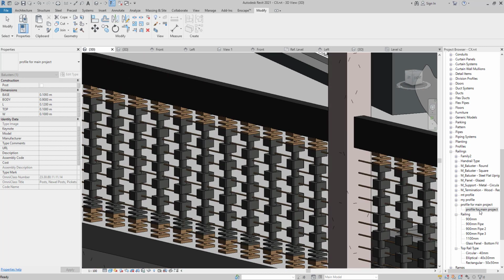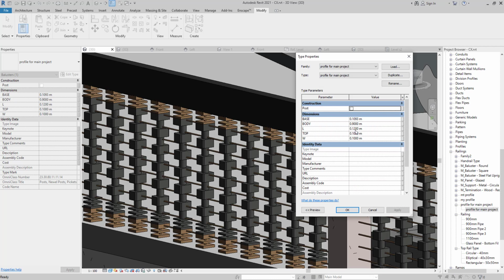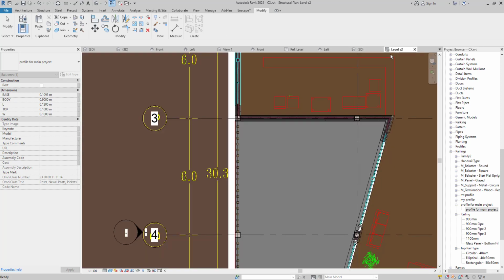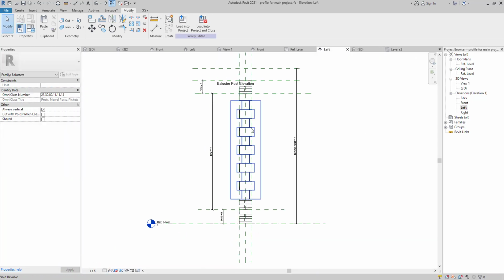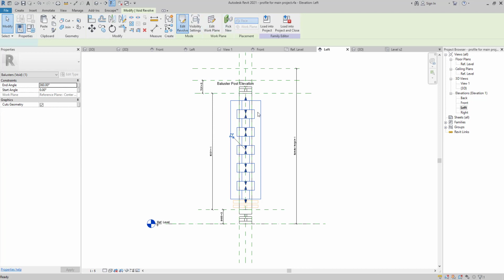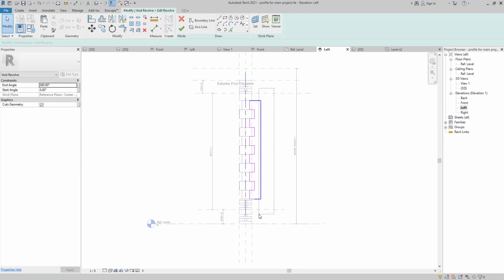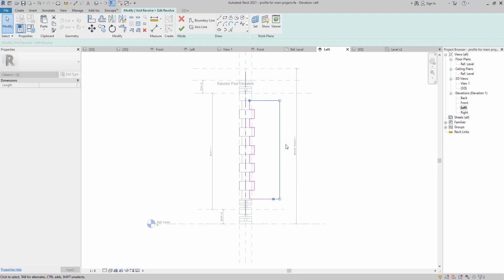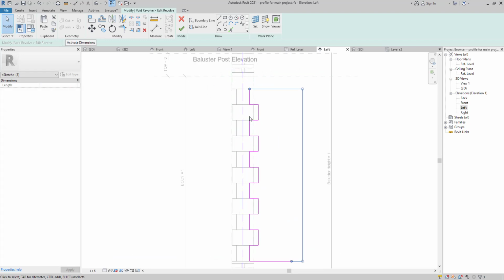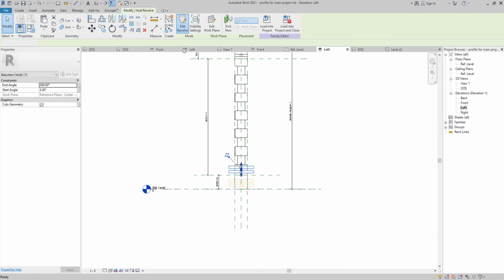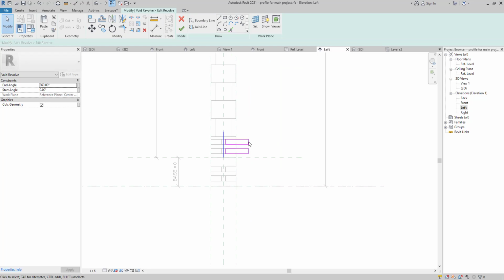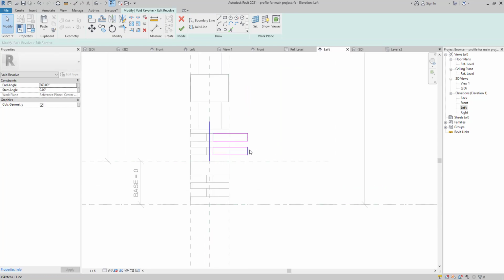Yes. And for example, if you want to be sure, you need to create your revolve much bigger. What do I mean? It means coming here and changing your revolve, edit revolve, you need to pick this line, take it out more, so whenever you want to make your shape bigger, it's going to be more effective. And after that, for example, you might need to do it for this one as well by just choosing these two lines.